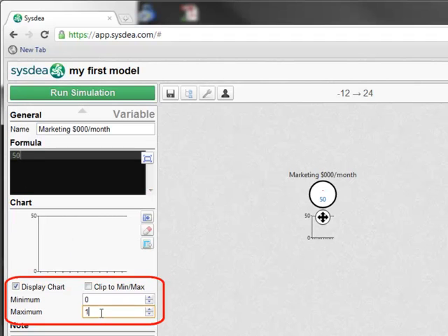You can change the scale of that chart. If I change it from a minimum of 0 to a maximum of 100, the 50 value appears right across the chart, and you can, if you require, force the chart to display within those limits. If you don't do that, the chart will auto-scale to cover the maximum and minimum that actually apply.